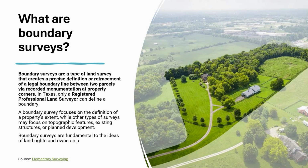Site surveys, where we're trying to look at existing structures, even initial phases for lot plans and things like that, we're not necessarily looking exactly at where the corners of each one are. You're designing it, you go out, you collect information for an area, you design the subdivision in CAD, and then it's when you go out afterwards, once construction has actually begun and you start setting monumentation to define those lots, that it really starts making a difference, crossing over from subdivision work to doing boundary work, or creating a boundary or retracing a boundary, which is going to be what's most common for any of you who go the RPLS route in relation to boundaries.